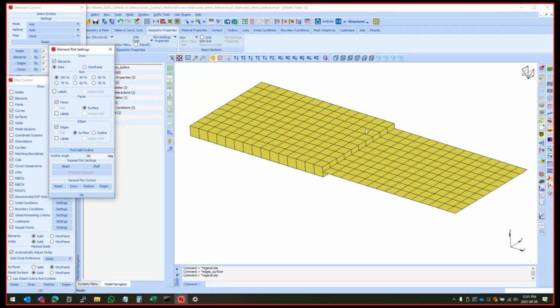Now, the thing is, this is something that we've wanted to do and needed to do for a long time in finite element analysis. It's the case where we've got some small part of a structure, let's say a joint or something, where using shell elements just won't cut it. It's not good enough. We need to model finer or with more detail. So in that case, we need to model that part as a solid and then connect to a shell mesh further away at some point where it's not too critical what happens in this region. I just need a really good load transfer and the correct stiffness transfer and so on across that.